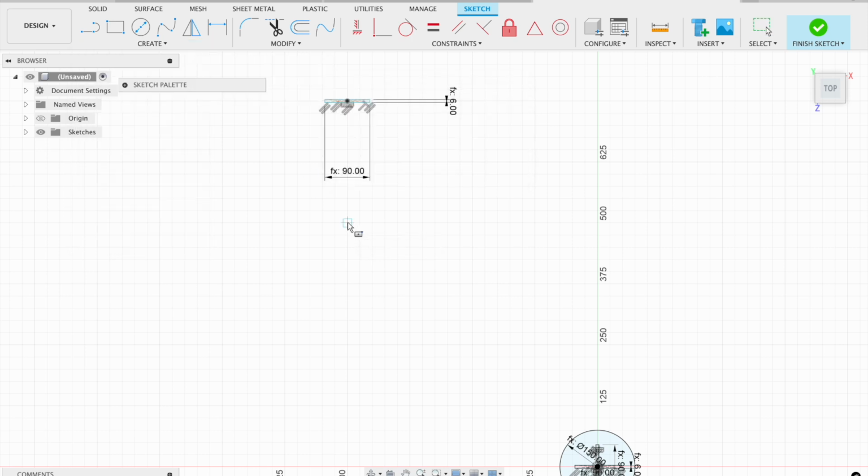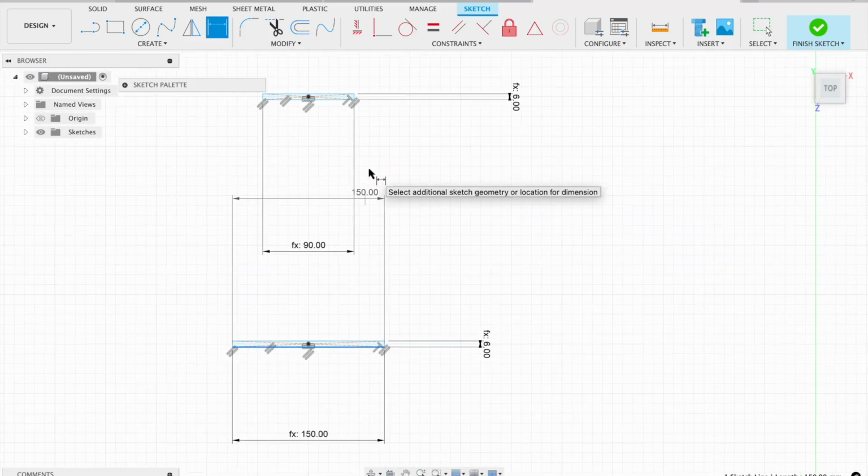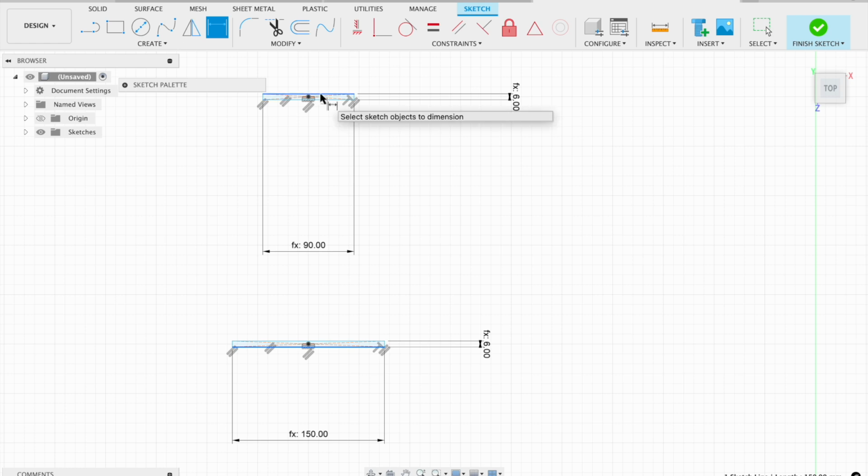I'm now going to create another one, and I'm going to center it on that same line that I centered the above rectangle. And the dimensions are going to be thick and then thick times 25. And that'll give me my 6 millimeter by 150 millimeter rectangle. I'm going to select the dimension tool or type the letter D, and I'm going to select the bottom line of my bottom rectangle and the top line of my top rectangle, and I'm going to change this to thick times 40.